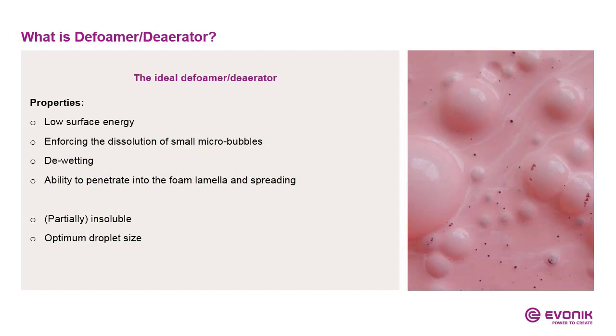The ideal defoamer or deaerator should have some of the properties as following. For example, they should have low surface energy. They should enforce the dissolution of microbubbles, for example, the TEGO Airex. And they should de-wet the surfactants. And they should have the ability to penetrate into the foam lamella and spread, just like the picture I showed you in the previous slide. That means they have to be partially insoluble and have the optimum droplet size.